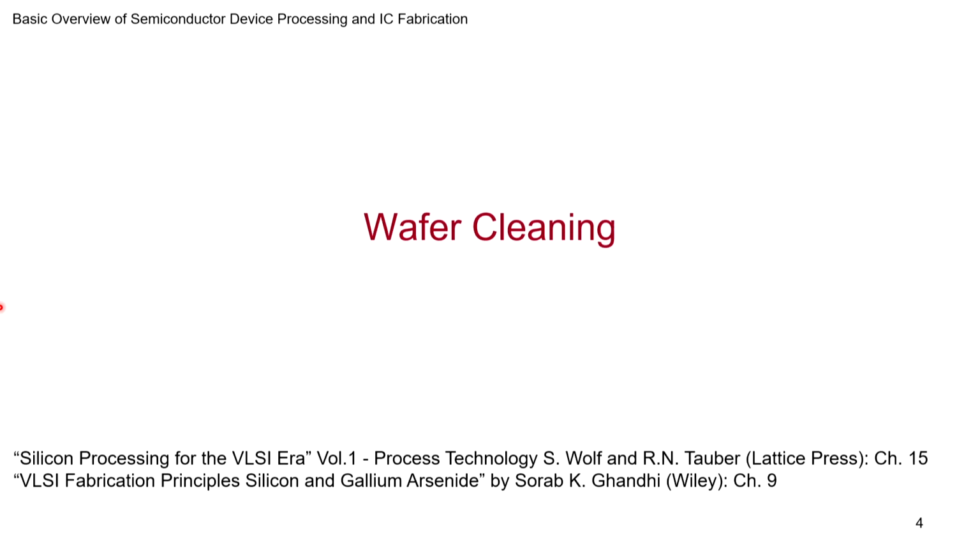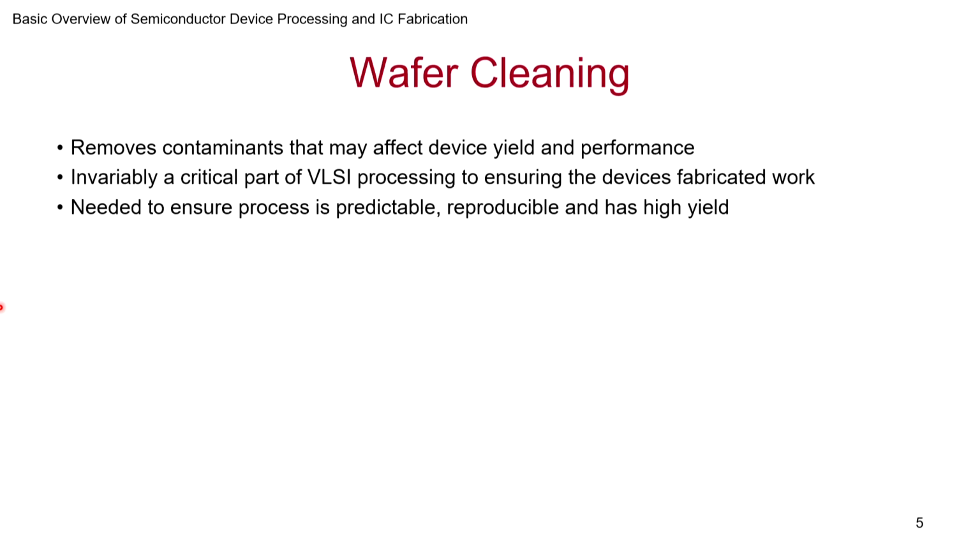So let's get started with wafer cleaning. Wafer cleaning is a very critical step. We may not realize it, but when you start with a wafer, you want to make sure it is as it should be. Ideally, it should be pristine. If it went through some other process, we would want to make sure whatever was the residue or some contamination that might have come in the meantime, as it was waiting for the next process, should be removed. So wafer cleaning removes contaminants that may affect the device yield and performance.